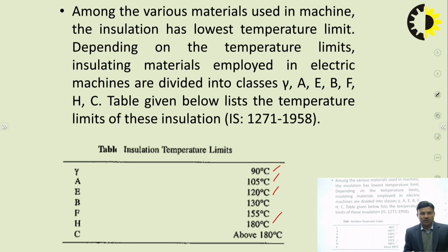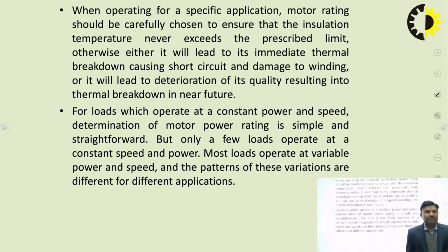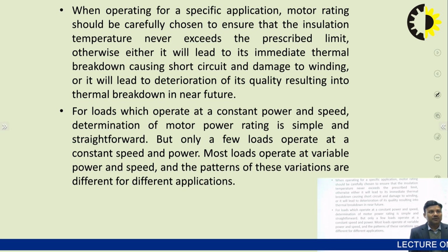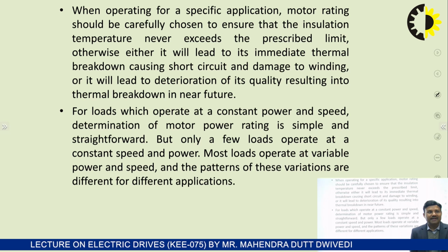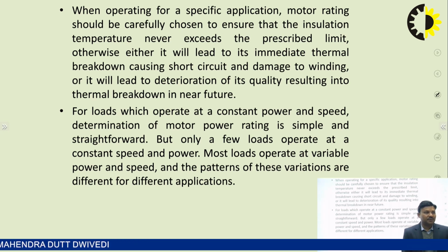When operating for a specific application, the motor rating should be carefully chosen to ensure that the insulation temperature never exceeds the prescribed limit. Otherwise, either it will lead to immediate thermal breakdown, causing short circuit and damage to the winding, or it will lead to deterioration of its quality, resulting in thermal breakdown in the near future.